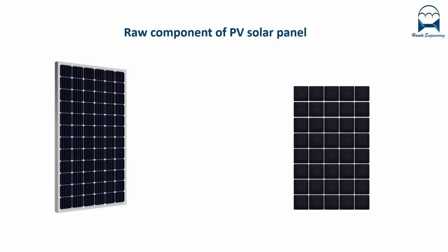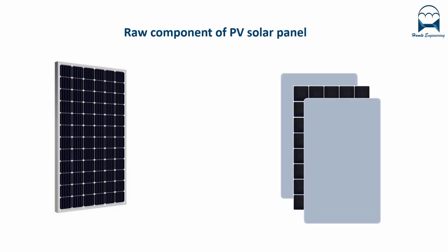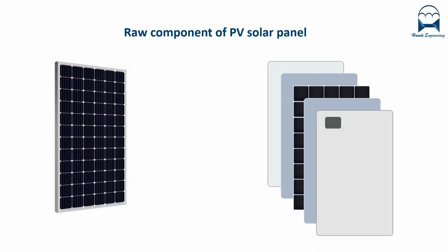Have you ever wondered what the structure of a photovoltaic module is and what the main materials are? There are many solutions available on the market and many raw materials that can be found, but the philosophy for manufacturing solar panels is the same for everyone. If we try to describe the structure in a few words, we could say that a photovoltaic panel is composed of a series of photovoltaic cells protected by a glass on the front and a plastic material on the rear. The whole of it is vacuum encapsulated in a polymer as transparent as possible.